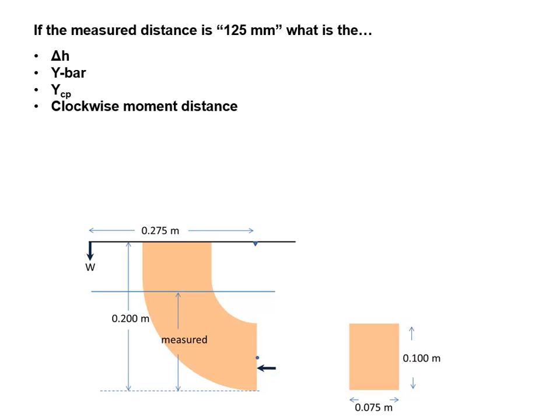This is the theoretical force on this side. For mass 325 grams, what's the actual force? Okay, so first of all, that's 0.325 kilograms times the acceleration of gravity. That works out to 3.1883 newtons. So that is the force that is coming down here at W. That's the weight that had been applied.